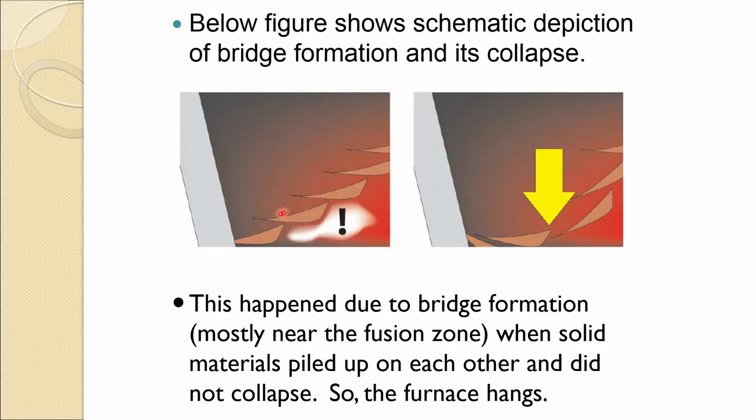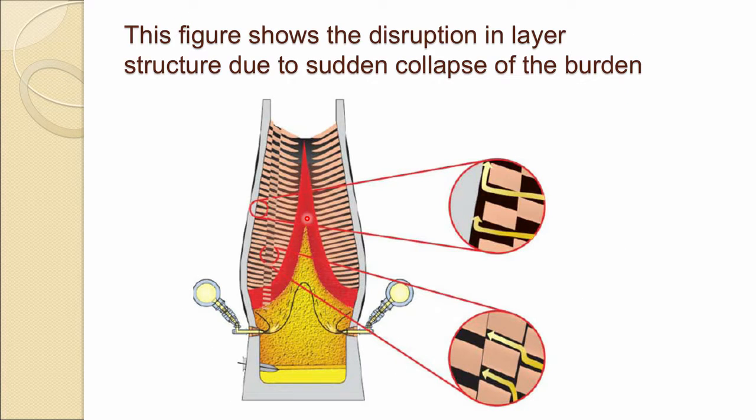As you can see in this figure, which is more of a schematic, the arc is forming and it keeps on building, and that situation deteriorates. Once this becomes bigger and the material weight keeps on increasing, suddenly it falls, and that is called slipping, and that disturbs the whole thing. In the next figure you will see what may happen.